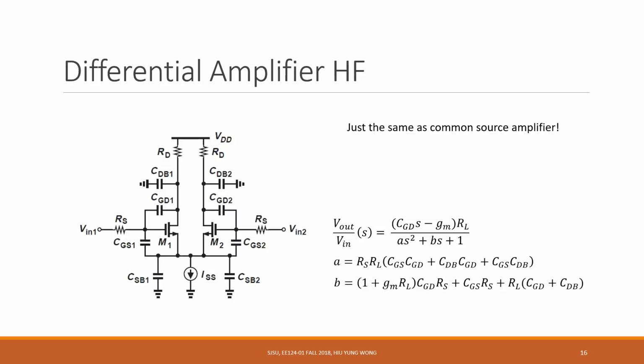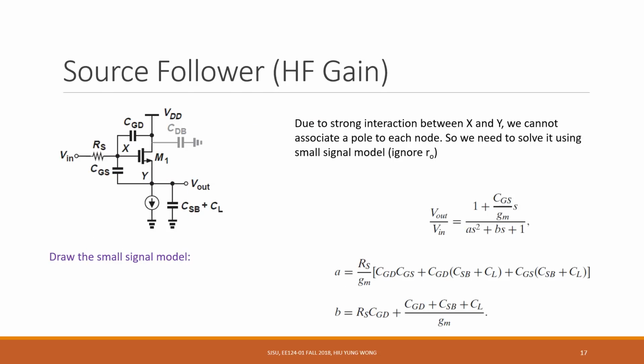Okay. Finally, the differential amplifier looks very complicated, right? But after all, remember we can use the half circuit technique, then it is just the same as the common source amplifier. We have exactly the same equation. Okay, so just to let you know about this.